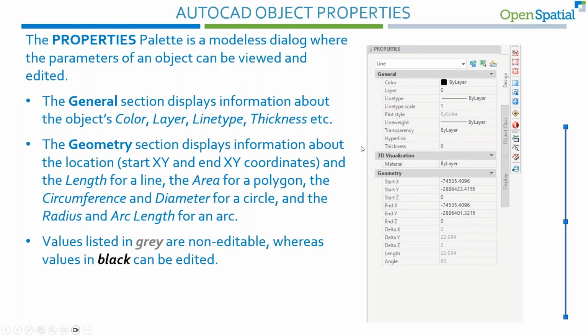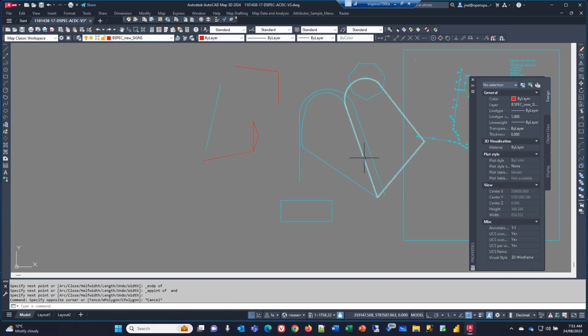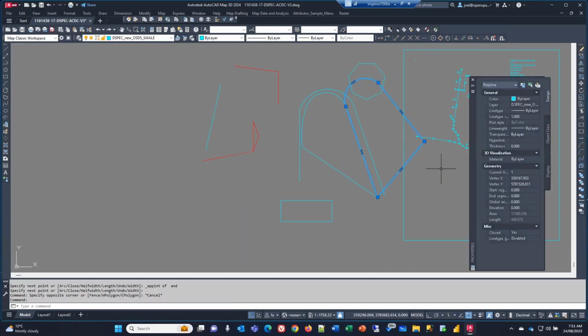So if I go and look at anything, what I will do is go to this polyline. So if I go and say in there, here you can see these grayed out ones, so I can't modify that. But what I can do is go to these vertices. So if I say, well, that's not quite there, that should be a 9, I can modify it in there and it will modify the geometry for me. Now, the other thing is I can also step through my vertices.